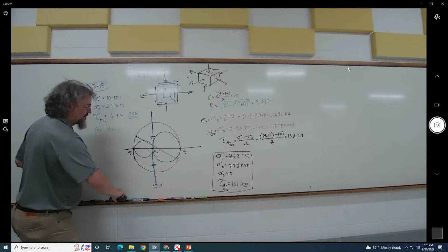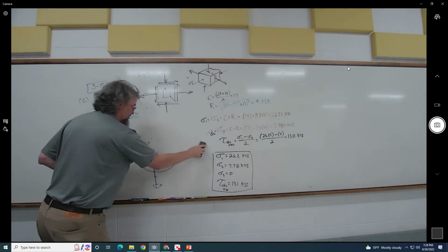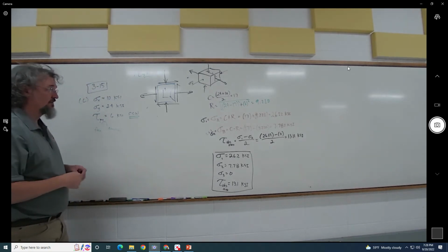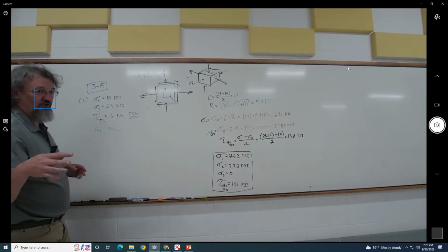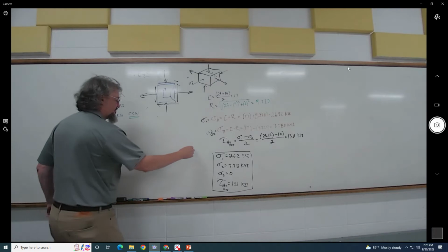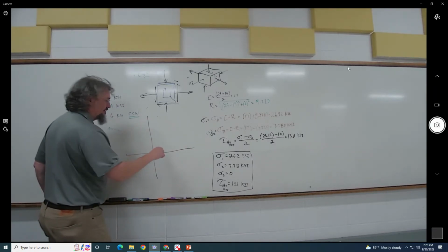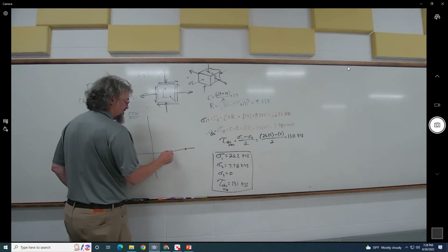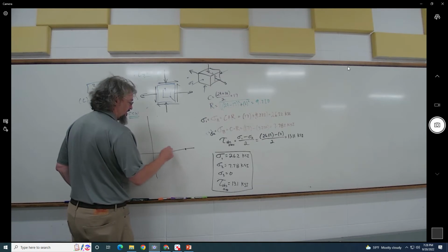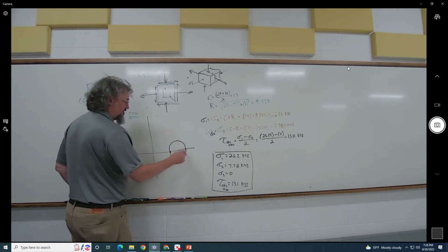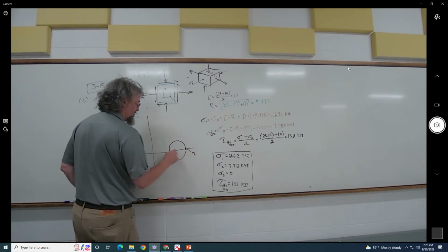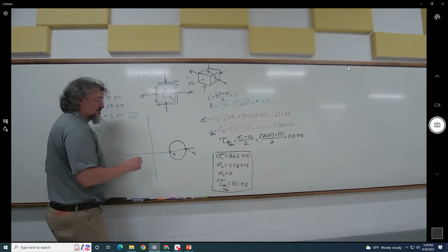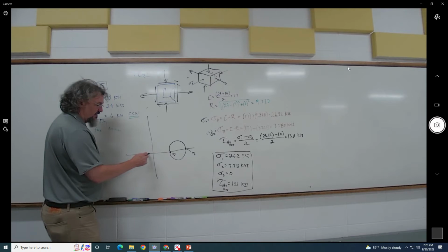A lot of times, by the way, because of the way that pressure is going to create stress in the tangential direction, the hoop, and the longitudinal, that radial is going to be pretty small compared to the others. So if there was only tangential and longitudinal, one thing to note is that they are always twice, or pretty close to being twice each other, right? So let's pretend there's no shear on there. So this guy right here, he's the tangential, and he's going to be the longitudinal right in there. Right, and they're both tension. But we might have one over here where that's the radial.